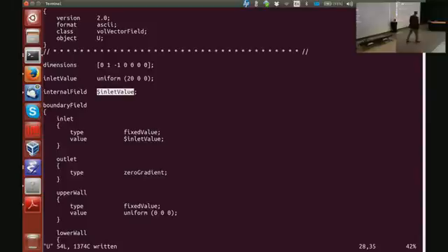Okay, you see what happened here? Inlet value is my keyword for a dictionary, but I want to use it many times. So any keyword can also be expanded. Okay? So down here where I say internal field equals $inlet value, it says, well, grab whatever was under inlet value and use it, both at the inlet and the internal field.